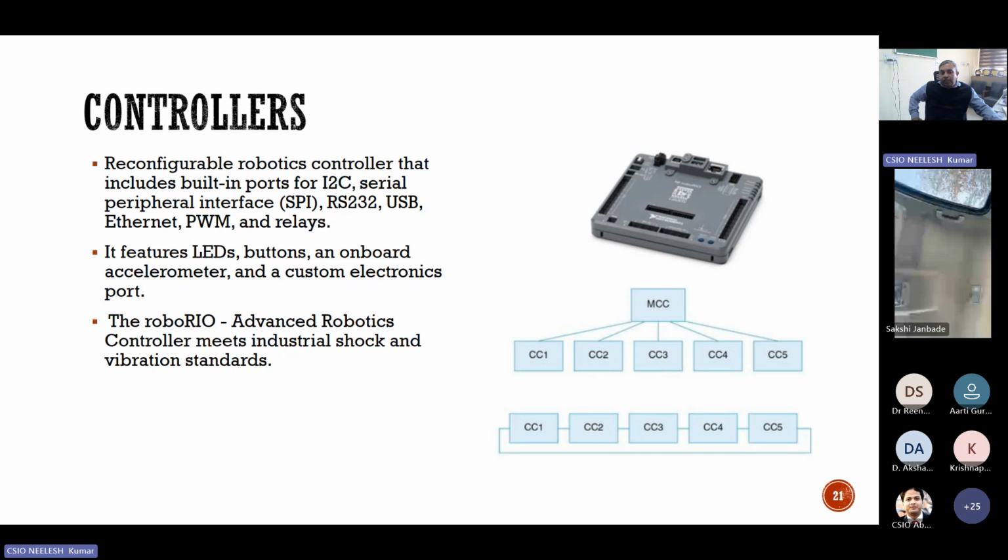There are different communication protocols because every sensor talks in its own proprietary language. Some sensors are SPI interfaced, or some are RS232. Most of the industrial controllers really talk in the older fashion. And when the data bandwidth requirement is high, they talk on Ethernet communication protocols also.